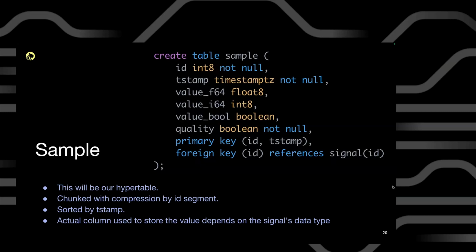But at least these three divisions are important. You have a sample that is a pressure, so it's a float, and you can have another sample which is an alarm, so it can be a boolean, activated or deactivated. But you have to take into account that, in theory, you are adding overhead by having three new label columns instead of one value.